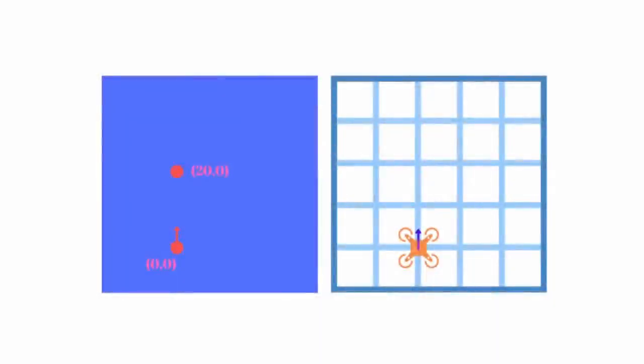In this chapter, we are going to look at how we can map our drone. Now, this is also known as odometry. The idea here is that we are going to use the velocity information to find the distance, and we will also use the angular speed to find how much angle the robot has or where it is headed. And based on this information, we are going to get the X and Y coordinates. So we will take the distance and the angle and we will convert it into Cartesian coordinates so we can plot it in a graph.